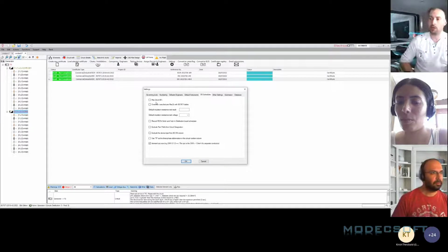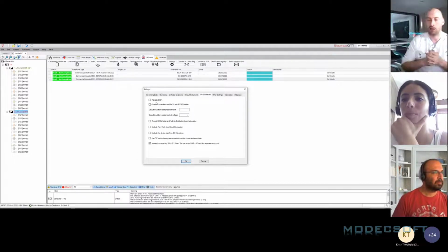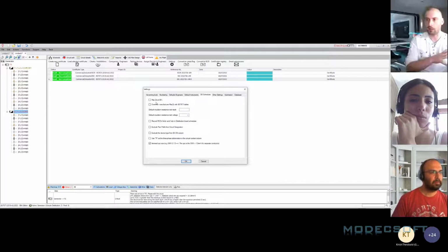This obviously goes back to pre 18th edition, where we had Appendix 14, which had information and calculations where you would put in your 80% value in terms of checking against your maximum ZSs. That has since been removed. When the first version of the 18th edition came out, the calculation in that appendix is now different.